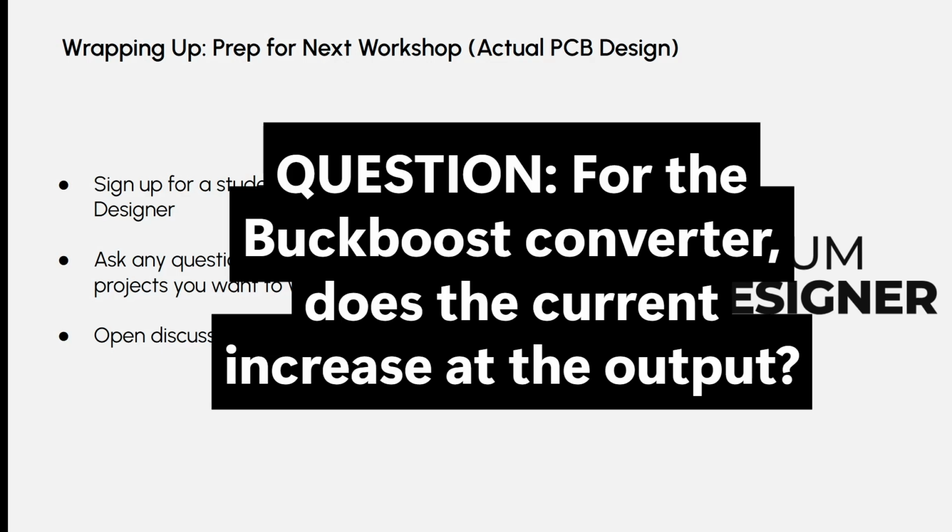Yeah, for buck boost conversion, you're decreasing the voltage. Do you have to worry about increasing the amount of current? Yes, absolutely. Power has to always be maintained, because of conservation of energy. Let's say you have 20 volts on the input and 10 volts on the output. If you are drawing 2 amps on the output at 10 volts, you are only going to be pulling 1 amp on the input at 20 volts, for 100% efficiency. So you're right, you can generate much higher or lower currents depending on the direction you're going in.